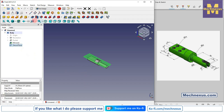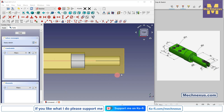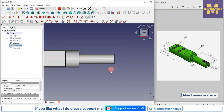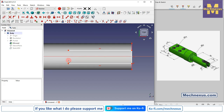Now select the datum plane and click on the sketch, and here first we will create a slot. So once we are in a sketch we do not require the datum plane, so we will hide it and we will click on the project geometry to project this edge, and here I will simply create a rectangle and I will delete this line, and I will provide the symmetric constraint to this point.